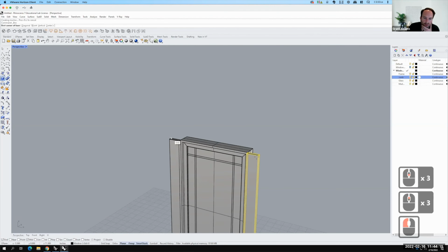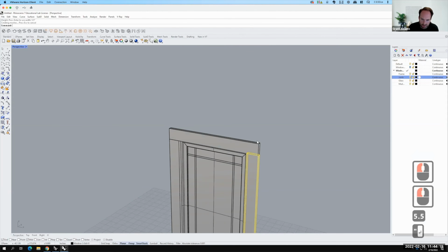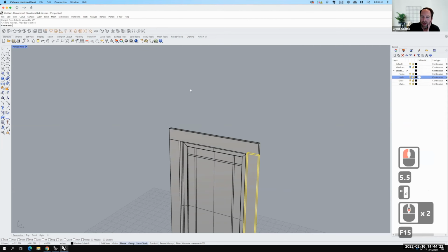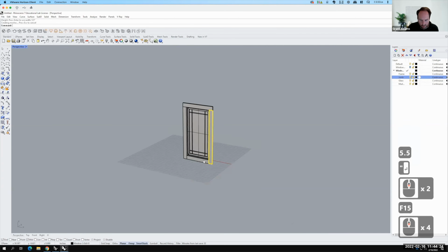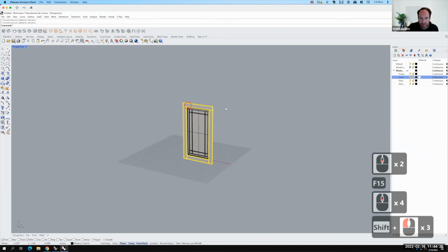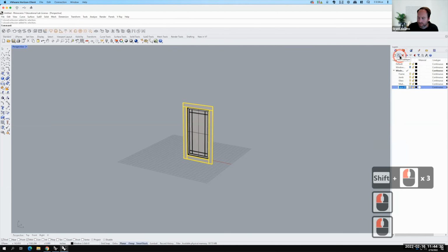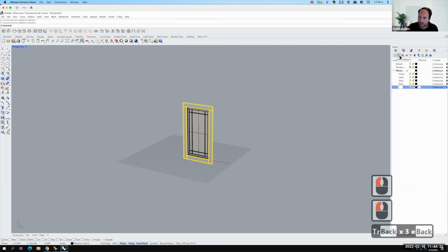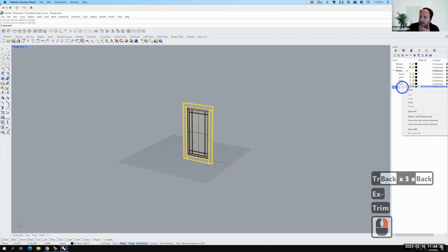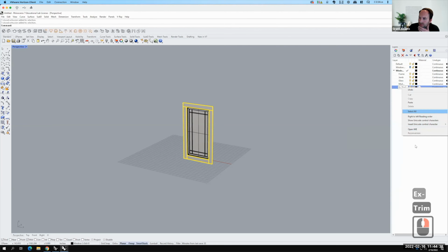So we can go all the way across the top. And that would be 5.5 inches. And so these objects would all be trim. So I'd create a new sublayer here for trim, or maybe exterior trim. And then I could right click and say change object layer. Sorry.